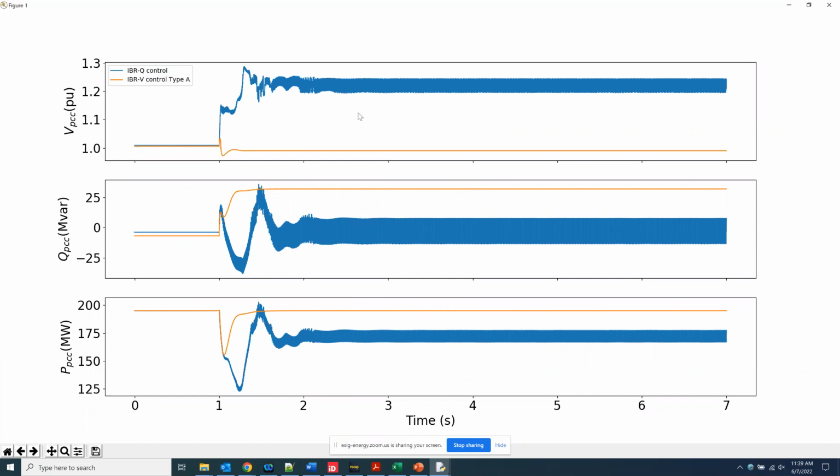Here again, in some way, it is still riding through the first 2 cycles. And this is actually a traditional type of inverter control that we have today on our system. There's nothing new in this inverter control that we're talking about. We have not yet progressed to the newer forms of grid forming control that have come up to the system, or come up in research literature, and some manufacturers have products. This is the same traditional type of inverter control that we have. We're still able to ride through the first few cycles. And of course, the type of instability that manifests is completely different, because there's no rotor mechanical mass, there's no electromechanical time constants, everything is electrical.